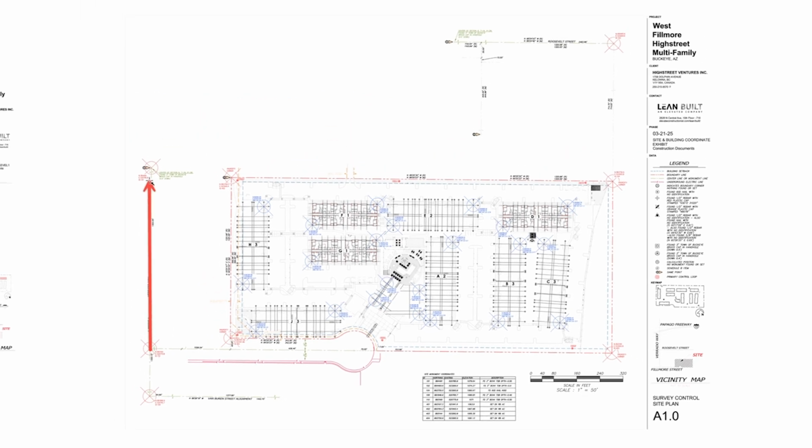Now, I'm going to draw this with arrows, and I hope this makes sense. The surveyors we hire will come out and actually traverse through the property lines back over to the basis of bearings and include that in a loop. I don't know how they'll pick up this third point, but they'll do it somehow, and basically verify that the basis of bearings matches the property corners. That is important because we want to make sure we're not in separate coordinate systems.